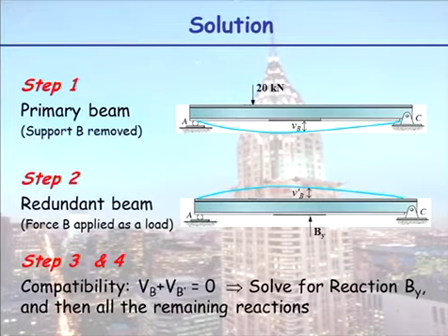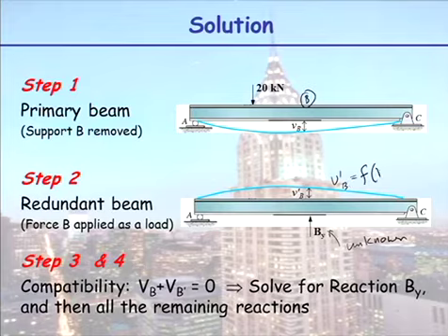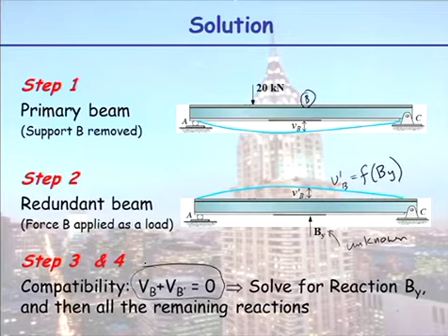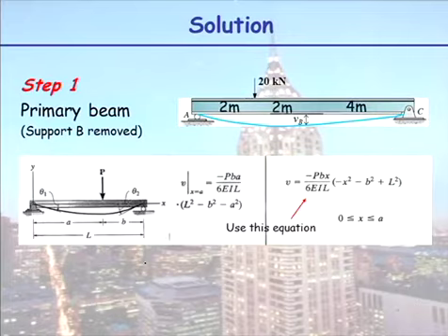So what we now need to do is calculate this point here, point B. So we're removing it, but we're going to calculate this deflection at B. And then we've put it back here as this By, which is our unknown. So when we calculate this deflection here, B dash B, that is going to be a function of our unknown reaction By. And then when we equate them in our compatibility equation, that's where you'll solve for By. Make sense? Okay, let's get some numbers happening then.